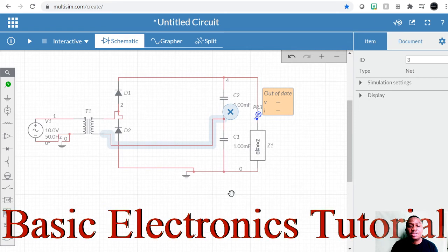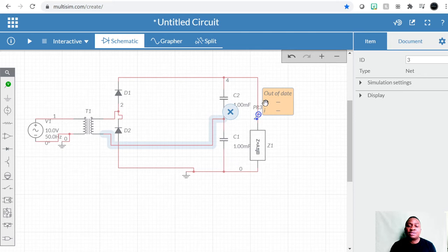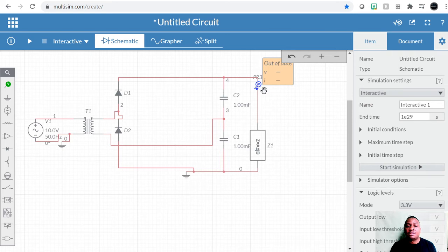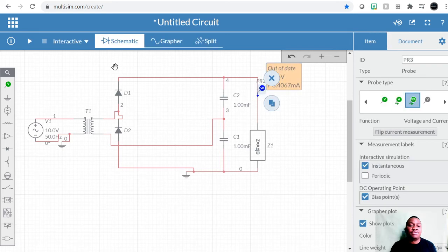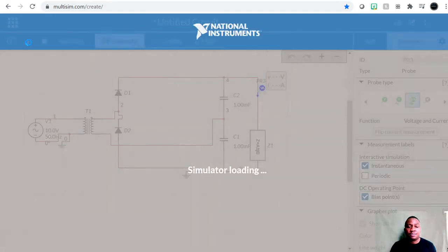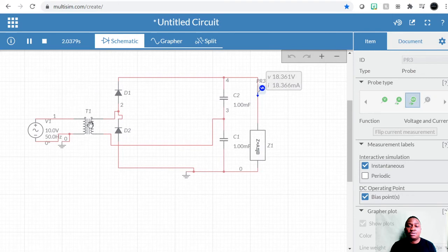Alright. So in this case, we're gonna get the voltage doubler function. So let's make sure we put the meter in the right place. Okay, I think this should be fine. So let's run it. Alright, so right here we have 10 volts, and over there we have about 18.2 volts. For a voltage doubler this would have given us 20 volts, but we're losing about 2 volts.